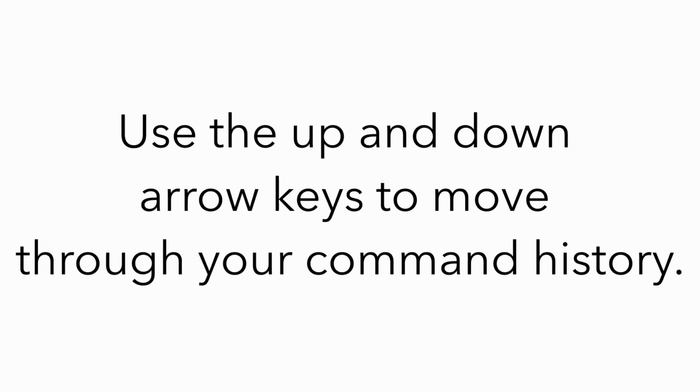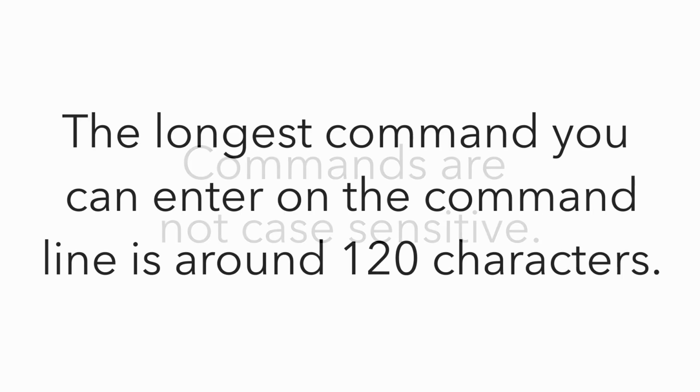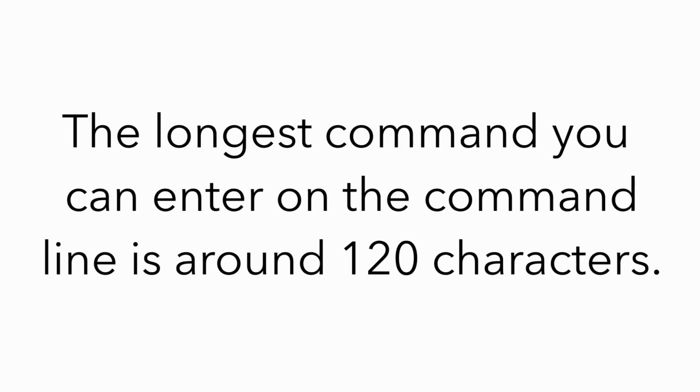Finally, here are some tips. First of all, you can move through the previous commands that you've run using the up and down arrows on your keyboard. Secondly, commands are not case sensitive. Thirdly, the longest command that you can enter on the command line is 120 characters long. And finally, to run a command, you press the Enter key.